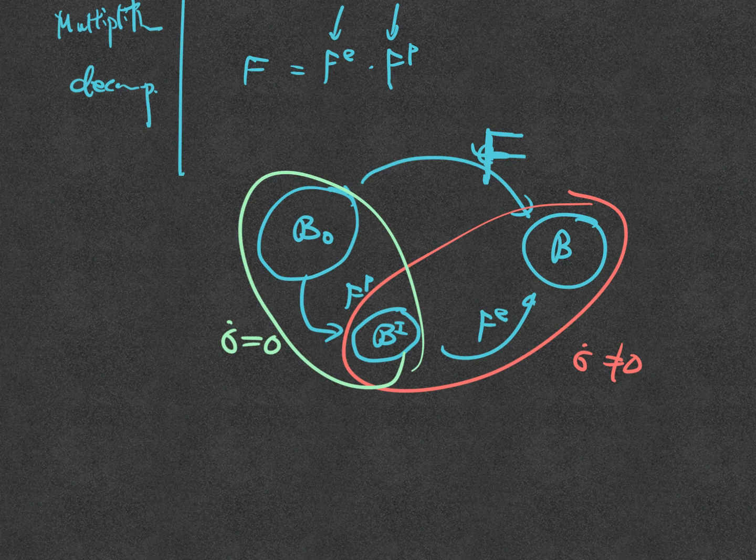Why does this thing exist? Why do I need to split it into two parts? It's because it's the definition of plastic deformation, right? You understand what I'm saying? I permanently deform something. What does that mean? If I remove the load, this thing won't go back to the original shape, right? So what does it imply if it doesn't go back to the original shape?